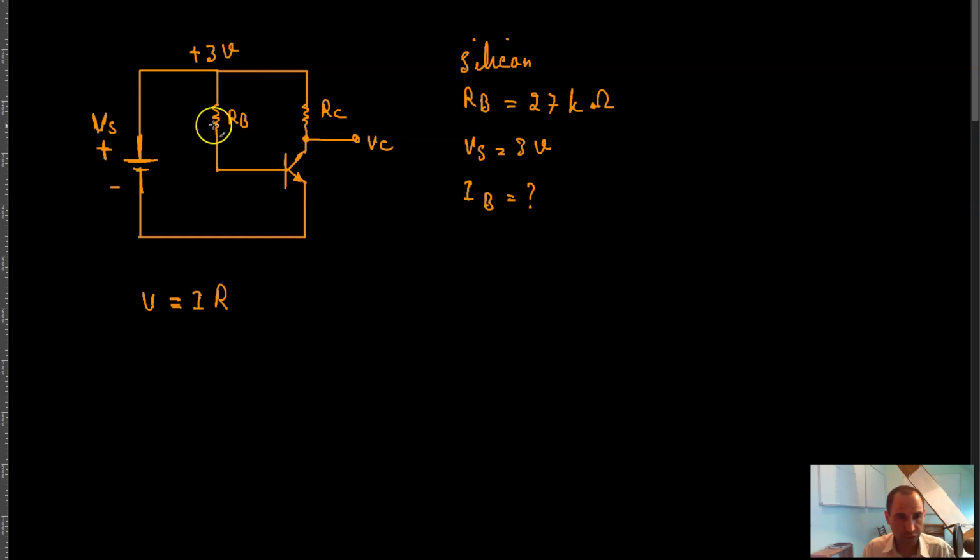If this voltage is 3 volts, then of course all positive voltages go to ground, meaning that the positive voltage goes through this resistor, through this p-n junction, the base-emitter junction, and then ultimately goes to ground. And so what that means is that the base-emitter junction and the resistor are connected in series.